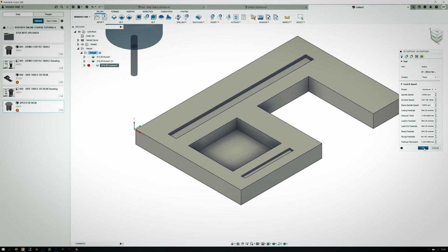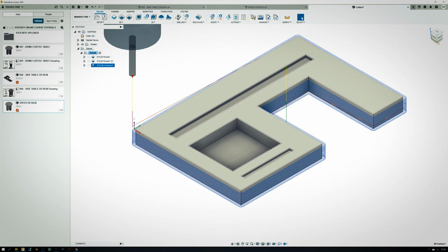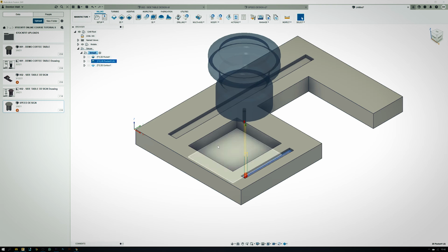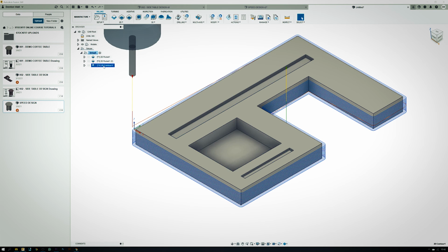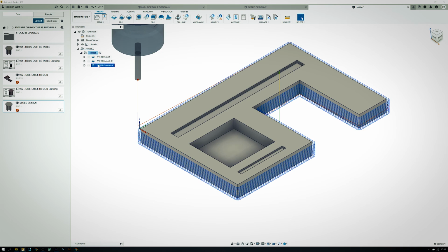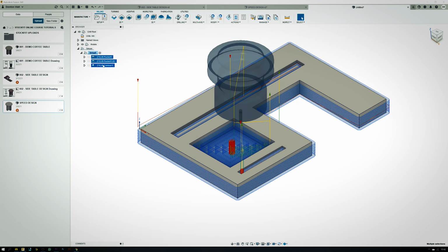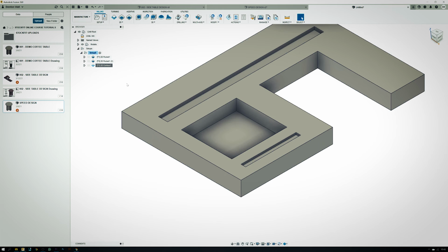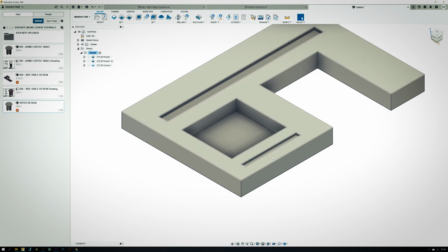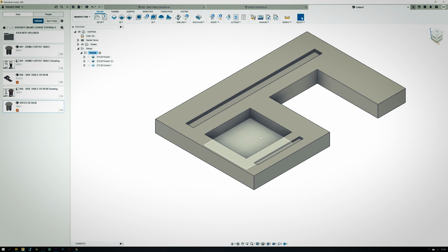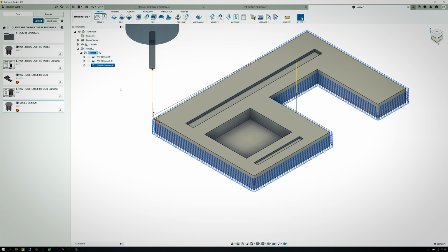It's also quite important that if you want to export the different paths, in this case we've got a 3mm path, and then we've got a 6mm path. Now it's important to make sure that you do not select all these paths together and hit export, because if you export all those paths together, it will export assuming that you've got tool change capability in your workshop. So if it's a single spindle machine, I would recommend exporting path by path by path.